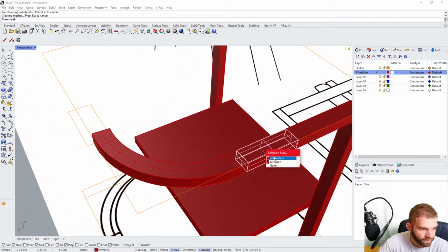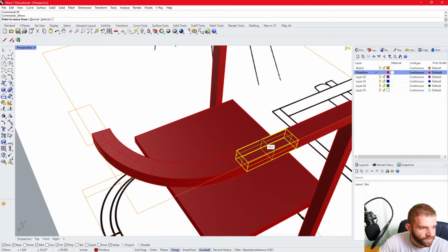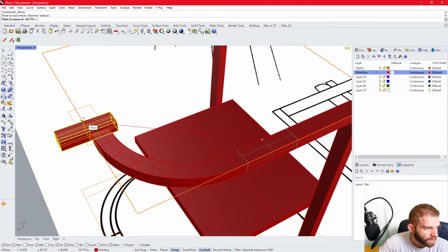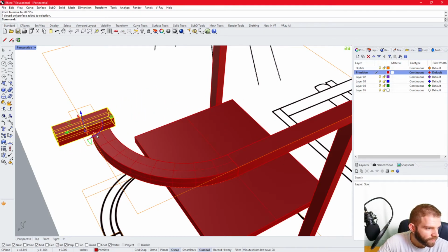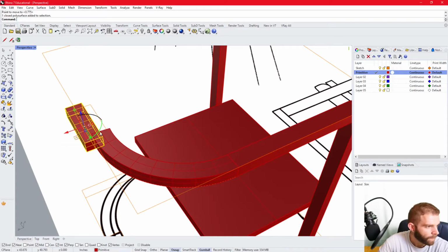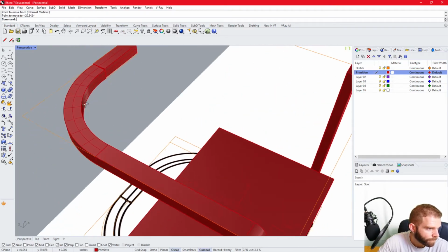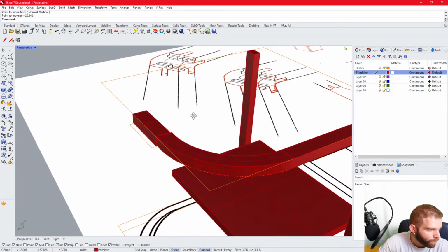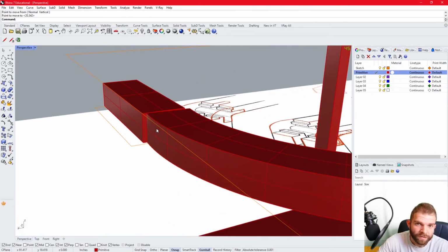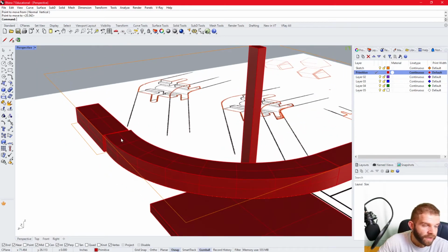So that's the only thing I've changed on this piece. But since it was aligned to the middle, I can easily bring it back to my constraint line by simply using the gumball, the move command, or the rotate command. And there we are. We could see now that even though I did that, my sweep did not meet that face properly. So I have to make another change.